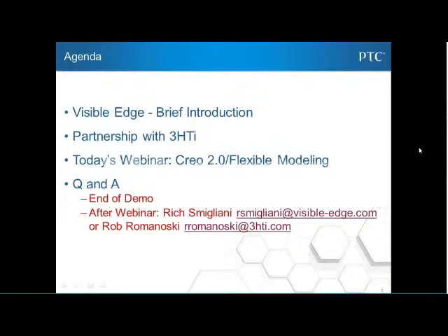All right. I have another question. What happens after saving this and, say, sending it to a customer that doesn't have a seat of flexible modeling? Yeah, they'll be able to open it up. They'll be able to look at the features, but they won't be able to manipulate them. Like they won't be able to go in there and edit definition, for example. But they'll be able to change a dimension that's there. They can edit dimensions, yes, but they won't be able to go in and say, edit definition, I want to pick a different surface, for example.